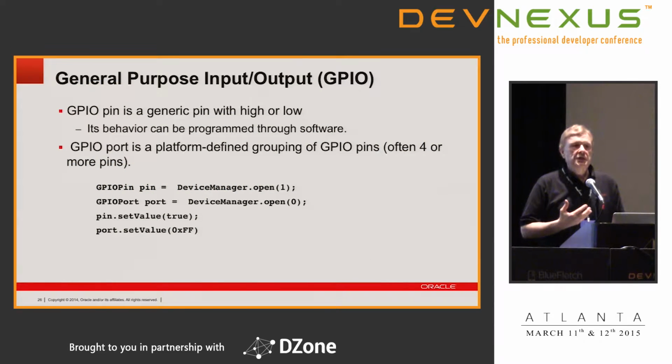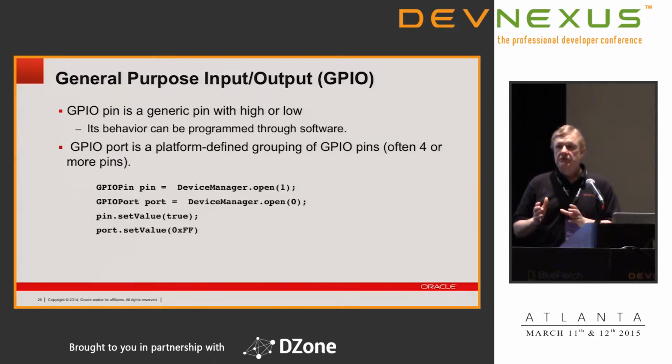So, some things about GPIO. Remember, there are several types of protocols. The first one is general purpose I/O, which is very discrete I/O, on and off, or you can group some on-offs together to create a port that could have more than 2 values. If you had 4 I/Os, you could have 16 values.